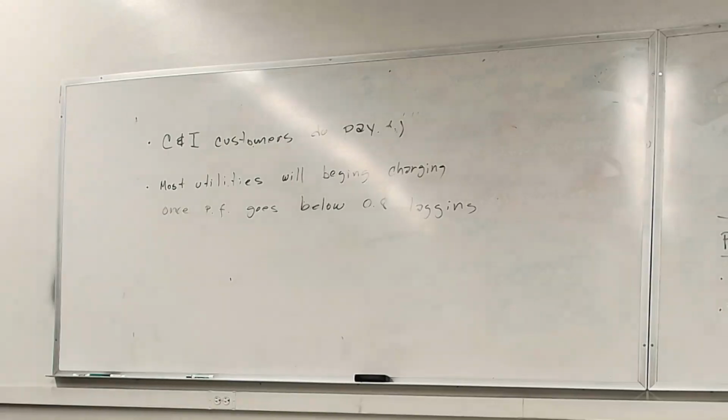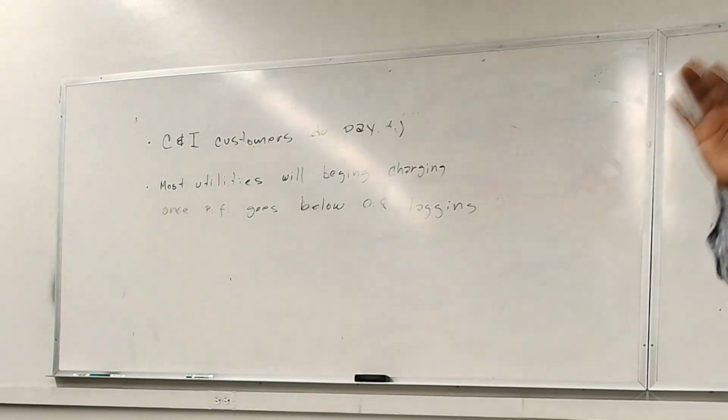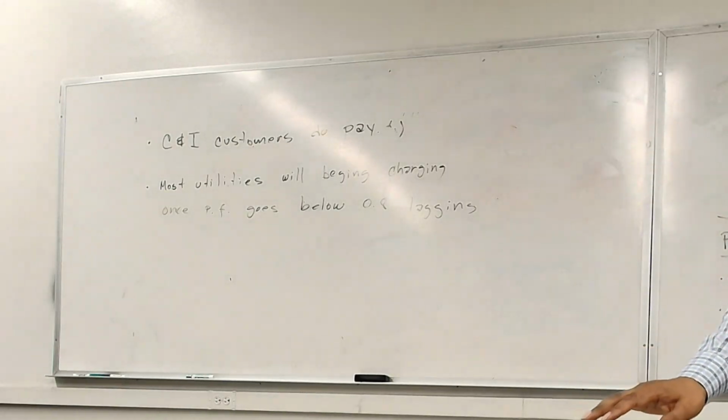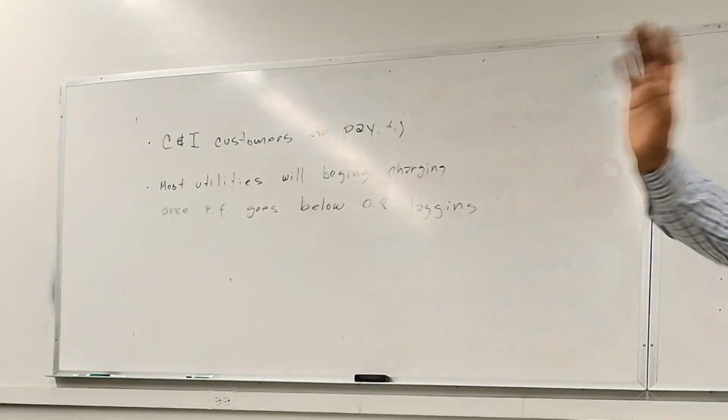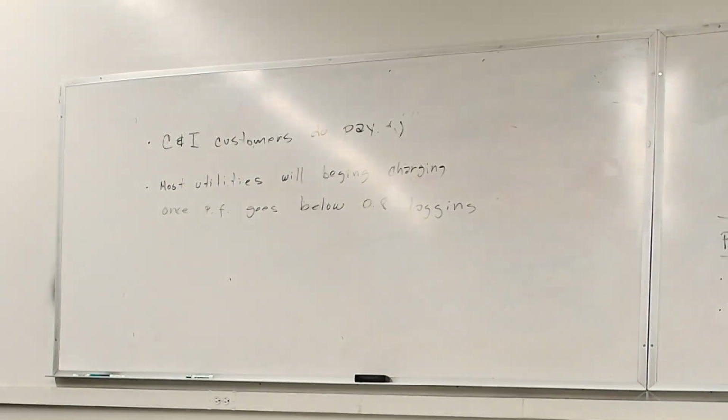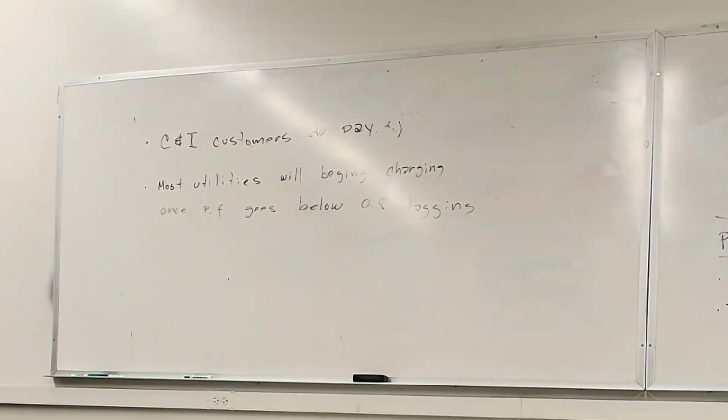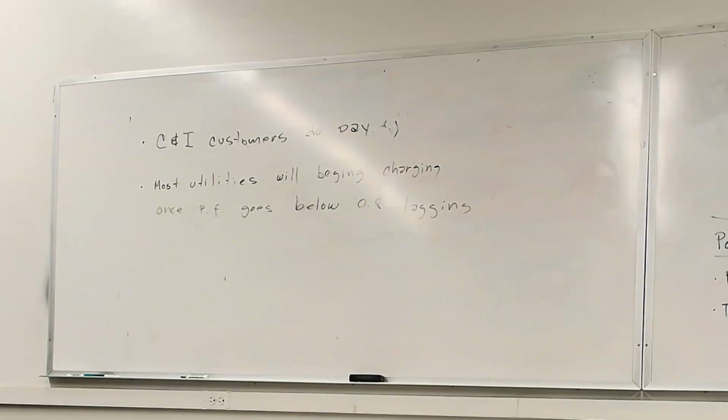Right? So residentials, you don't pay for it. The only thing you pay is the watts, the real power. Vars, free. Yes. So for industrial, let's say they have a big induction motor. Right. And there will be a lot of lag. Yes. And one way to do it is to just add capacitors to counteract it. Correct.